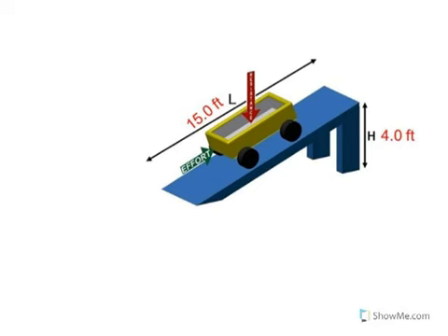In this picture, I have an inclined plane where I am pushing a cart up a ramp over the course of 15 feet. Pushing it up the ramp 15 feet allows me to raise the cart a total of 4 feet. Getting back to everything else that we've talked about, if I'm dealing with distances, I'm looking for an ideal mechanical advantage.